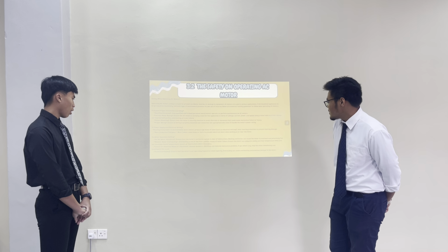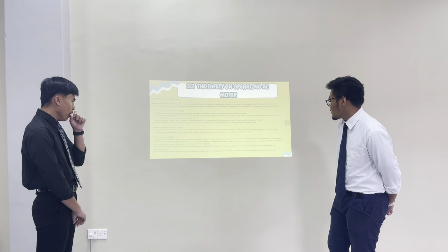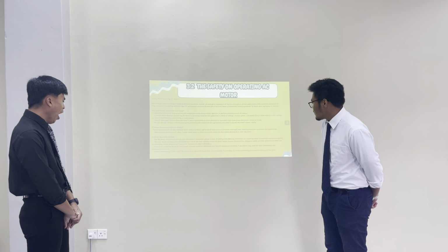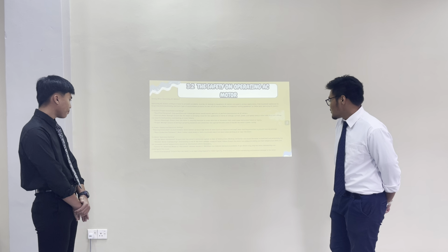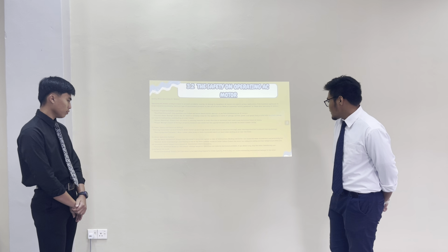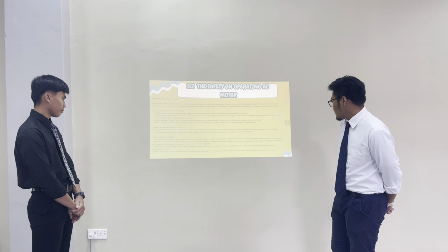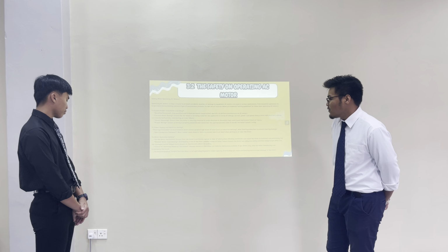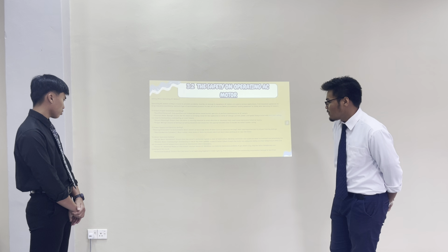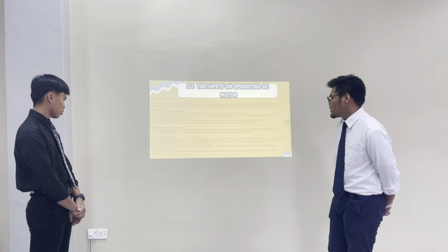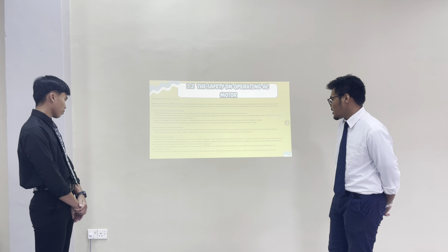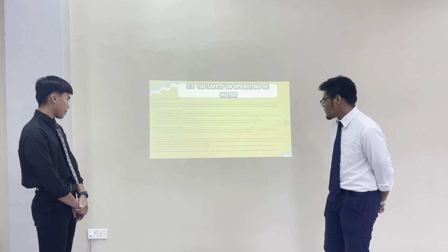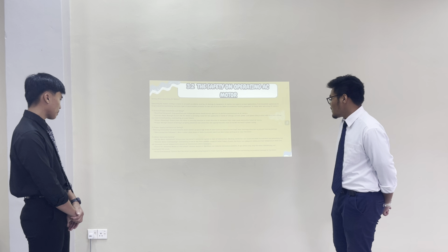Install temperature sensors or thermostats when necessary. Check for abnormal noise or vibration. Unusual sound or vibration can indicate a mechanical problem. If you detect any, stop the motor immediately and investigate the cause. Avoid overloading. Ensure that the motor is not operating beyond its rated capacity. Overloading can cause overheating and eventual damage to the motor.